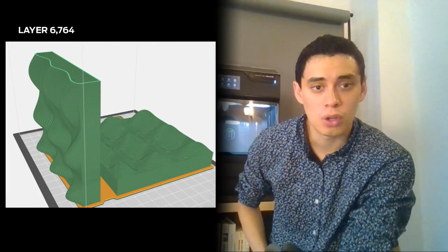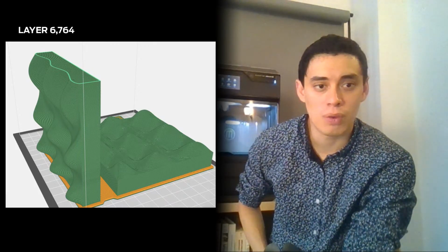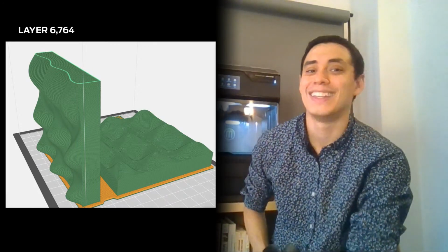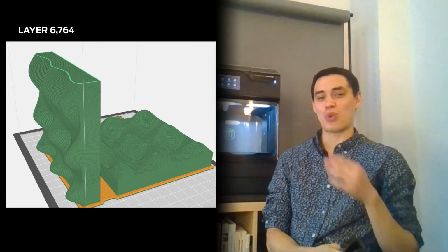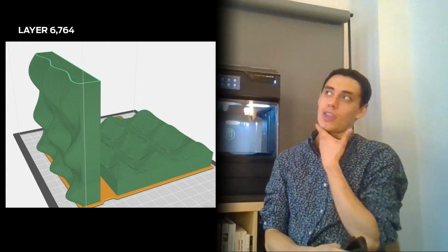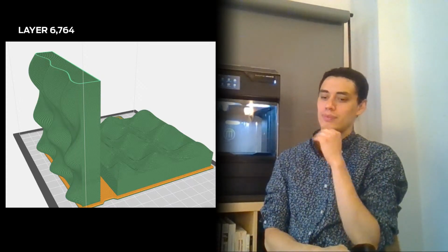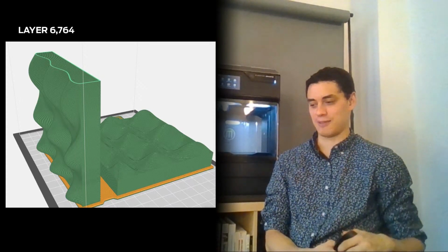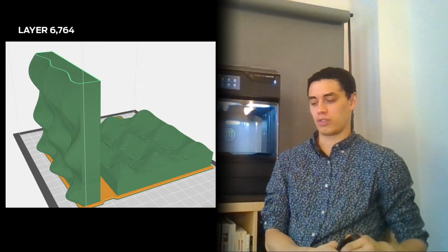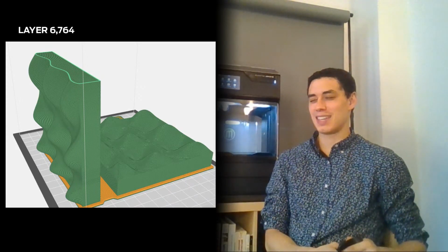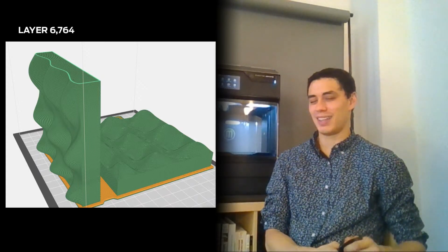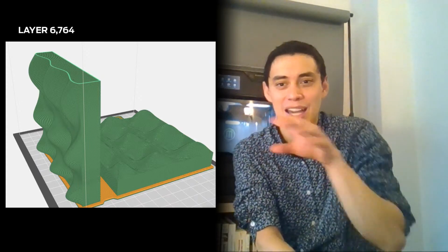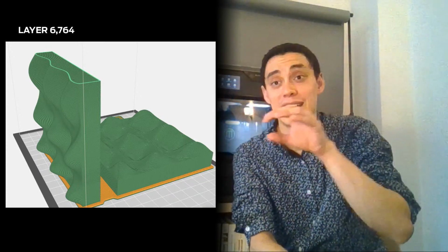What's a good workflow for making small changes to a Rhino model for printing purposes? Yeah, that's a good question. Because Rhino, unlike SolidWorks, once you've committed to a surface, once you've committed to the model, making changes can be a little bit tricky. So what I usually do is copy and paste steps of my model.